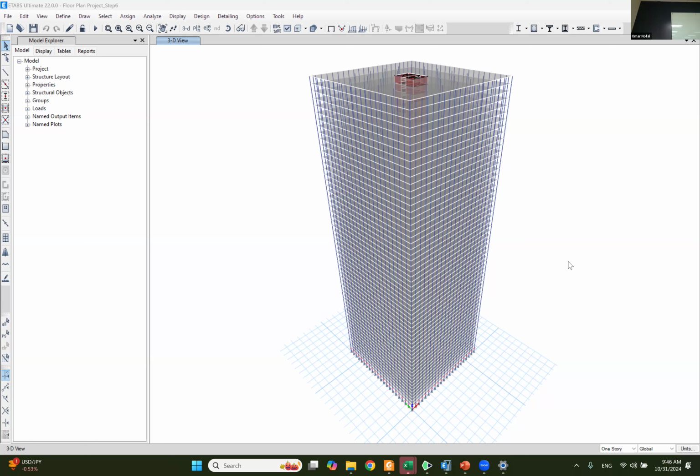So that's the summary of seismic analysis or lateral load analysis for buildings. It's all about load quantification, and that's what we do through response spectrum analysis. Once we quantify the load, we apply it to the building and run a dynamic model for the structure. Okay. All right.